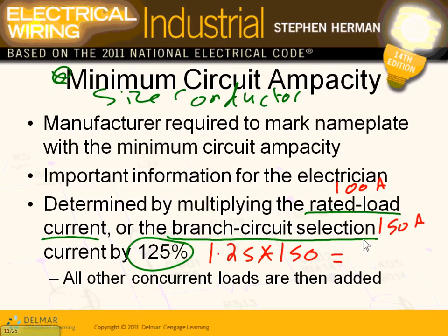So what's 120 times 100? This is for a refrigerant. Yes, this is for anything that has refrigerant going. Because earlier you said they take that into consideration, so you don't need to do the 1.25. You don't have to do it if you get the minimum circuit ampacity. You do it if you do not have the minimum circuit ampacity. If you do the math on this, guys, you're going to end up with 188. This is 188 amps. Cool? 188 amps. That's how you do the math.